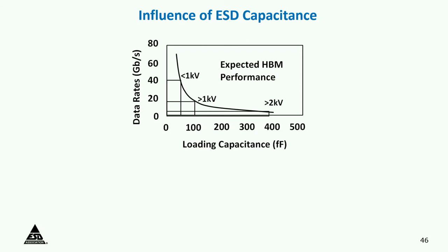Yeah, I'm not sure I understood all the question, but I do want to tell you that companies like Cisco that are building these high-speed systems, high-speed operation is more important than the ESD protection. So now the question is, well, of course ESD protection is needed. What do I do if I can only protect to 500 volts instead of 2000 volts? The answer is better control in the factory. Okay? Although I showed you a simple thing, they can control a factory to 10 volts. It is more expensive, but that's where the technology is going now. You have to control to lower voltages to get higher speeds.